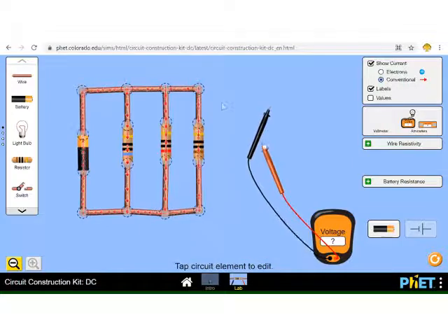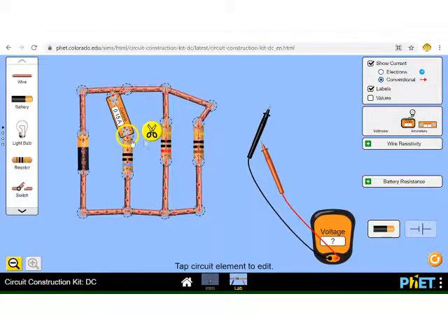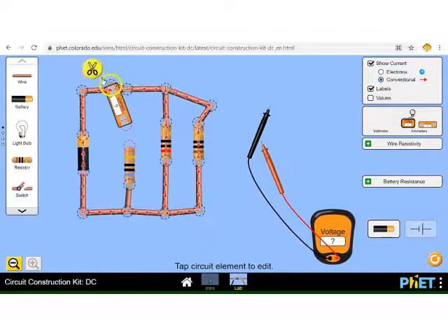Okay, next let's grab the ammeter and let's measure our currents and see do they match up with what we found. So through R3, our current is 0.9 amps. That's what we found when we did our problem. So I'll just take the ammeter back out. Like I said, this is a wee bit fiddly. Okay, I'm going to put my ammeter in with R1 next, and 0.15 amps, that was what we got when we did our calculation. Okay, pop out my ammeter.